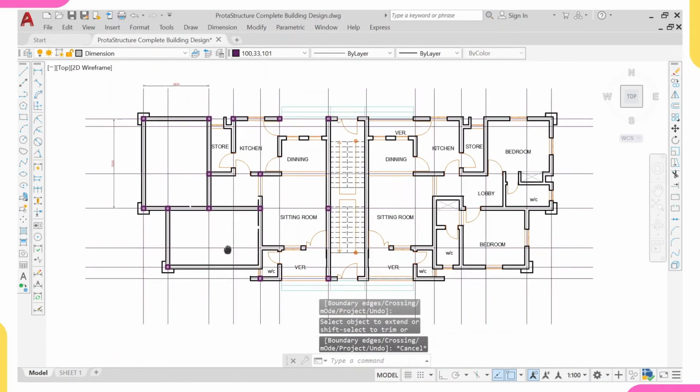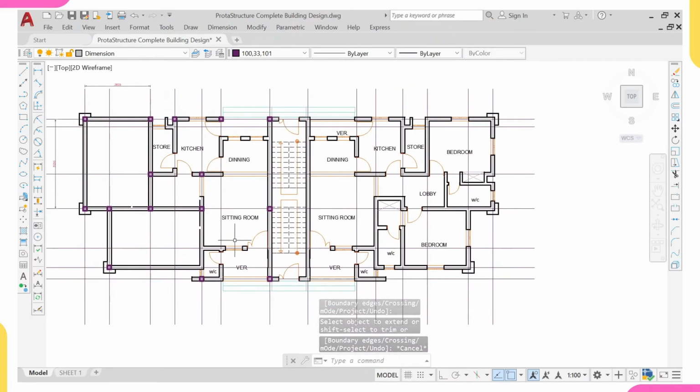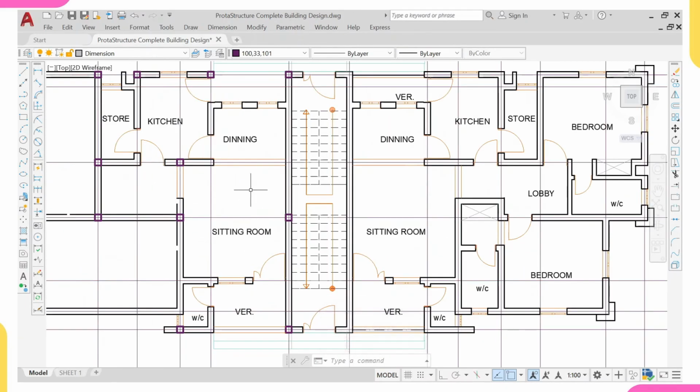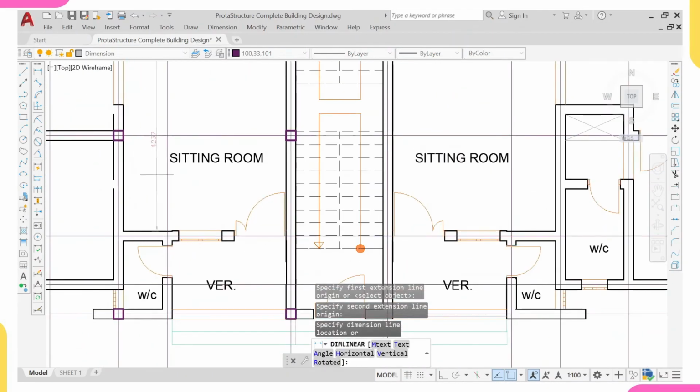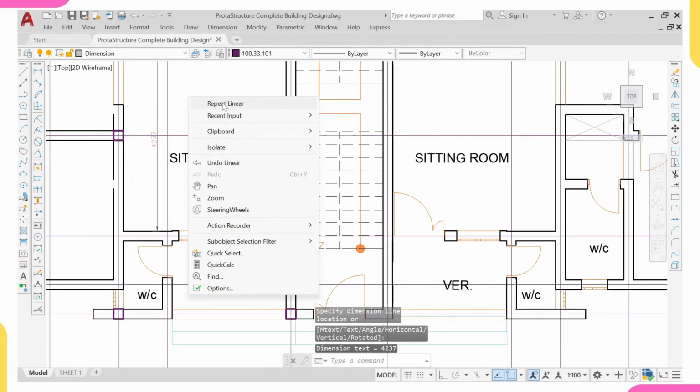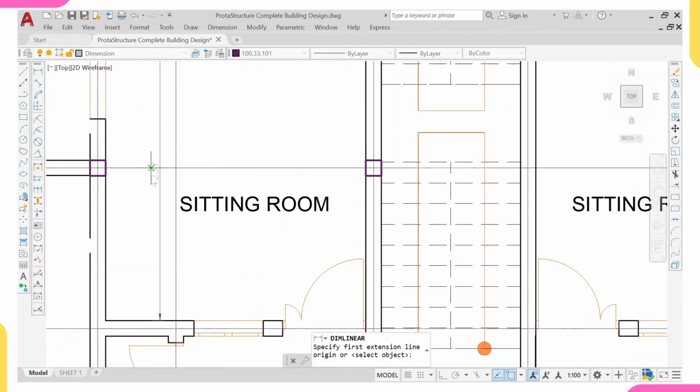So this is one panel, this is one panel. Then coming over to this point now, I want to make this sitting room one panel, and then this veranda and this toilet and bathroom and this toilet one panel. So I'll come and check what is my dimension to be sure it's no more than 30 meters square area. So I'll come and check from here to here. I'm having 4.23. This thing should be maybe 4.25.